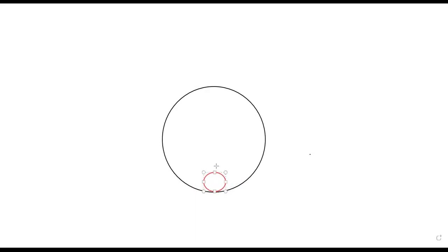So this position of the system, or the roller in this case, corresponds to the minimum potential energy, and the equilibrium of the roller in this position is said to be the stable equilibrium, because if it is displaced from its initial equilibrium position, it has a tendency to come back to its original position, because this position is of the minimum potential energy. Hence, this equilibrium of the roller is said to be the stable equilibrium.